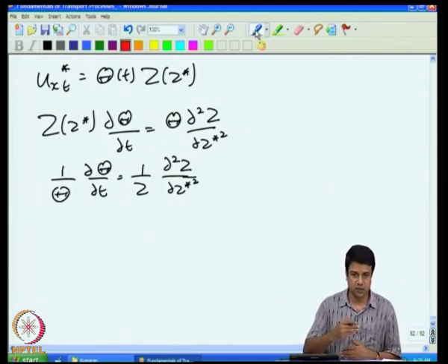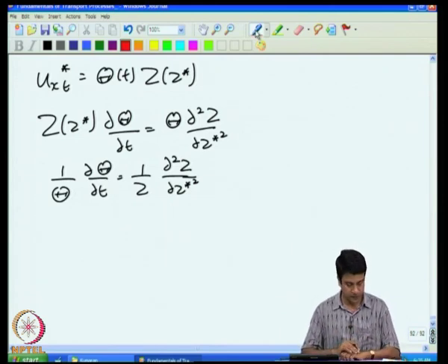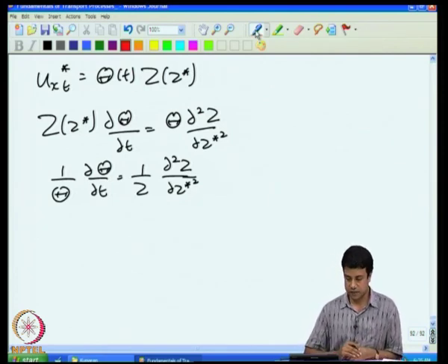u_z was equal to 0 at z equal to 1, I am sorry, t was equal to 0 at z is equal to 1 at z is equal to 0. However, when we subtracted out the steady part, for the transient part alone we had temperatures equal to 0 on both surfaces. And a similar reduction, because of that we got homogeneous boundary conditions on both surfaces.